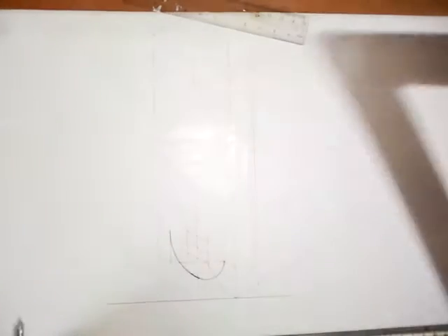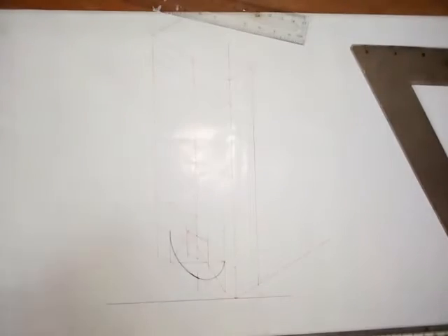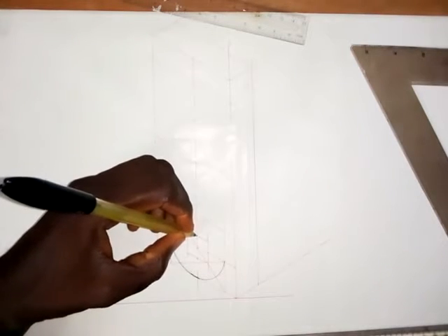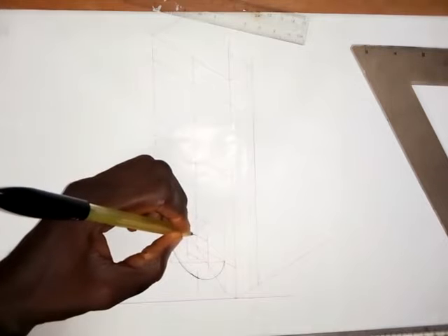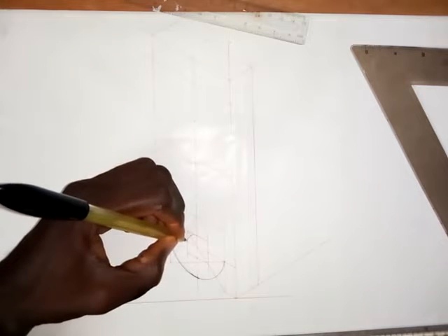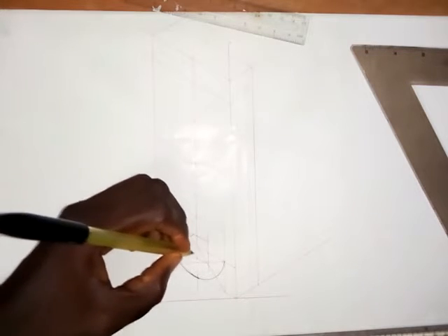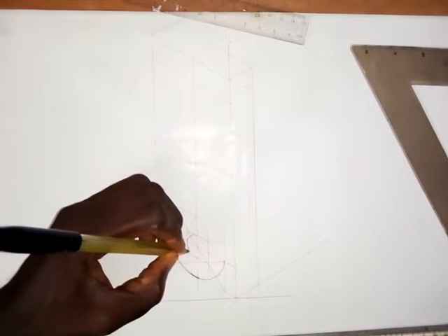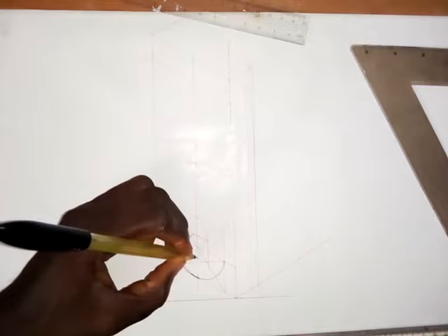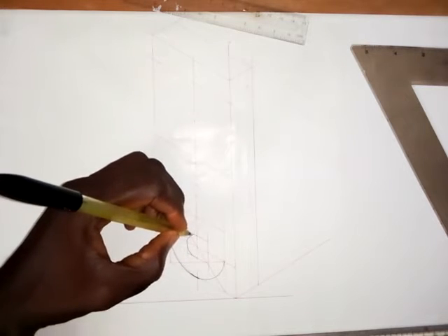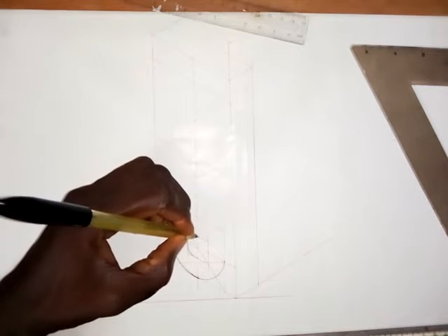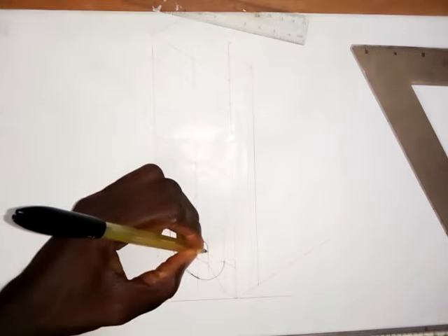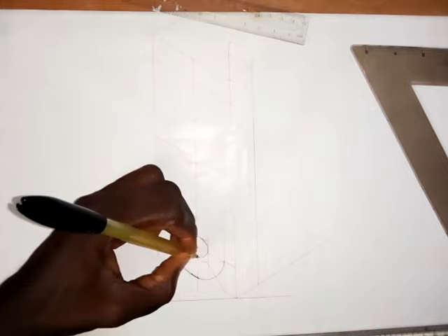Okay, so I'm going to draw the circle. This is what I do whenever I want to produce a small circle like this. I use my hand to produce the circle. It is not going to be an actual circle, it is an ellipse. So be very careful. It's going to give us an ellipse. Whenever I want to produce a small circle like this, or a small isometric circle, I use my hand to join these four points together. And that's what I'm doing now.